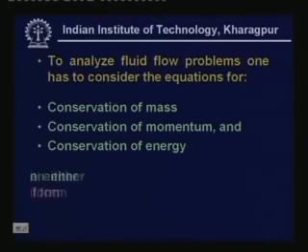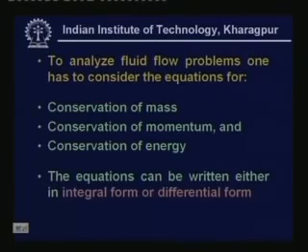Now depending upon the approach, you can write these equations either in integral form or in differential form. That means if you are taking a control volume and apply these conservation laws, you get integral form of equations. Or if you take a differential element inside the control volume and apply the conservation laws, you get the governing equations in differential form. In the present lesson, I will give you only the integral forms of conservation of mass and conservation of momentum.